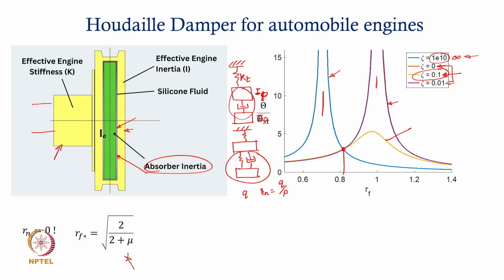And so if we manage now to adjust this damping ratio so that it passes through this point with zero slope, then you would have no very large level of torsional vibration. So the objective now is to figure out what this zeta optimum is, so that the graph of the response passes through this point with zero slope, okay.